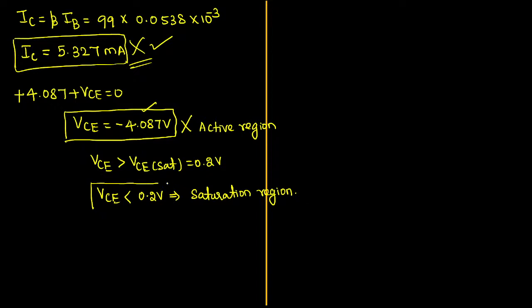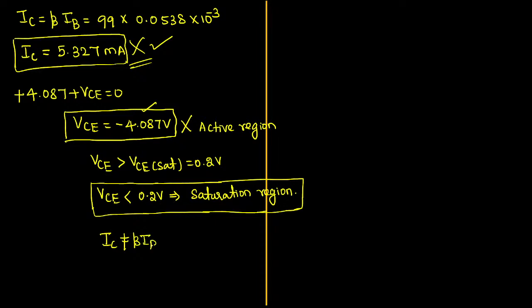Okay, sir. So when our transistor is in the saturation region, you cannot apply relations like collector current IC equal to beta times IB. That relation is not possible directly. You should not directly write this kind of relation. But what you can do is, since we identified that the transistor is in the saturation region, we know some default values. What default value? The collector-to-emitter voltage in the saturation region is fixed. It will be equal to 0.2 volt.